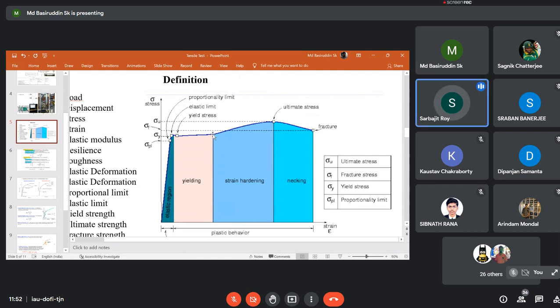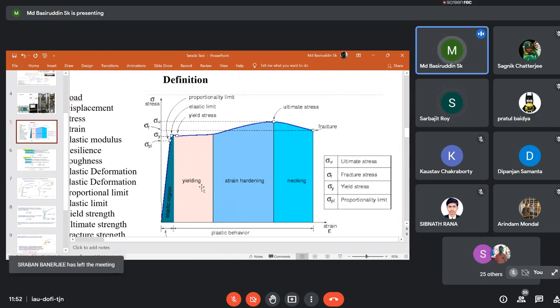So you have to draw a line parallel to the elastic line, right? Yes. Then we have to correctly measure the permanent deformations, or the true strain of the particular material. If I draw the engineering stress strain curve, then it is the engineering strain. If I draw the true stress strain curve, then it is the true strain.